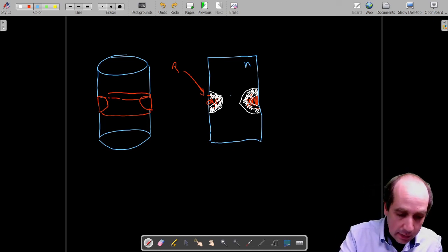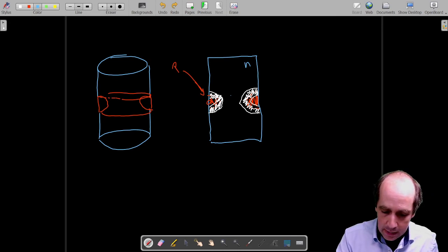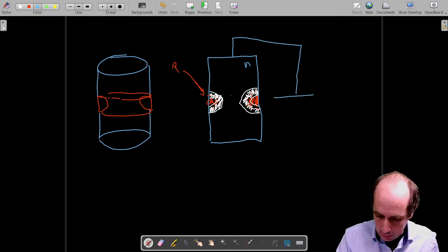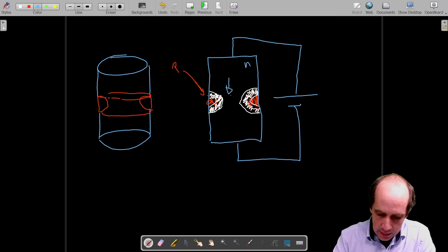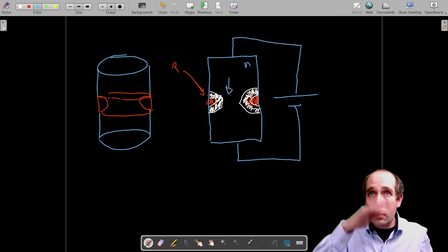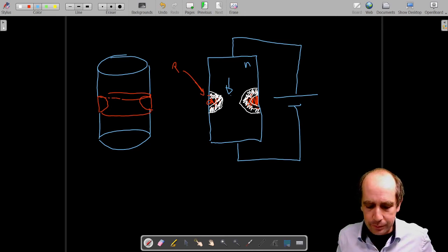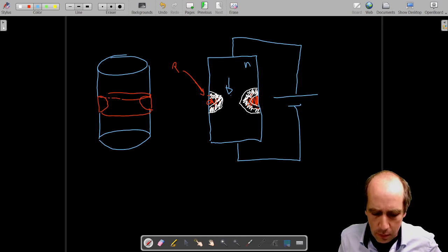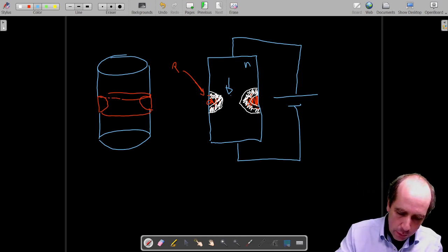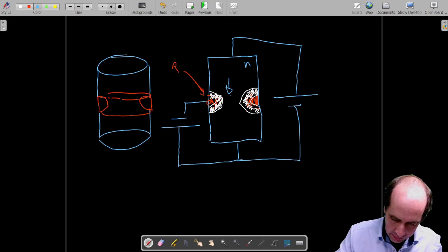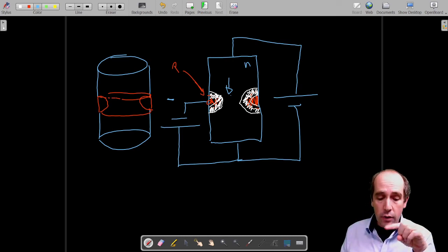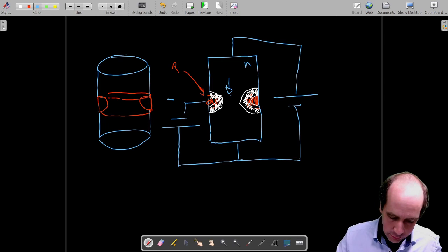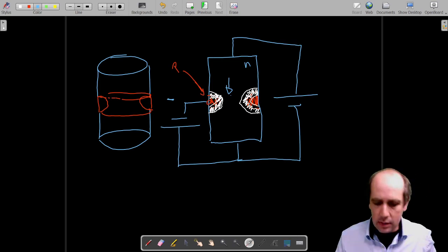Okay, so yet this is not completely closed, and in principle, if I connect a battery or a voltage source over here, a current will establish in this region, and current will flow through the circuit, even if the channel is relatively small. Okay. However, if I now put, let's say, a battery, and let's say we put it in these polarities here, so the minus sign is over here. So the minus sign will attract the holes that are in this little bit here and here. Remember, this is a ring around.